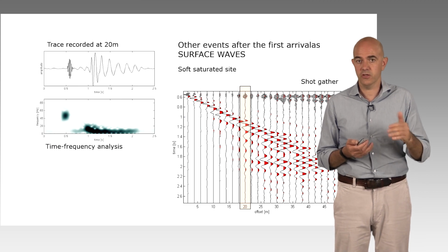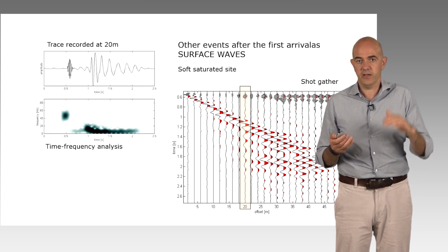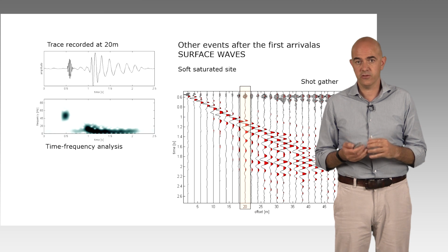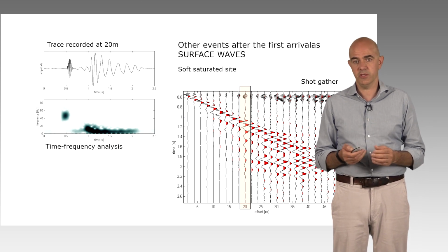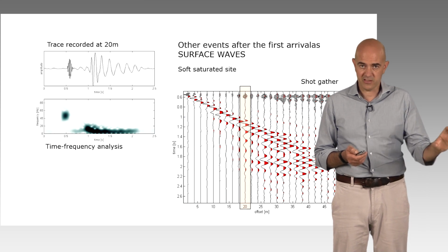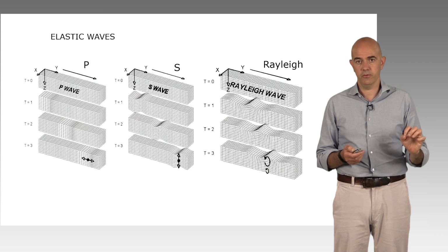And we are not interested in knowing that in many cases a saturating groundwater is at a certain depth. We are interested in getting the mechanical properties of the solid skeleton, of the matrix of the subsurface solid media. And the shear waves are extremely important for that. This is why for the site characterization and for many geotechnical problems, shear waves are the way to go.